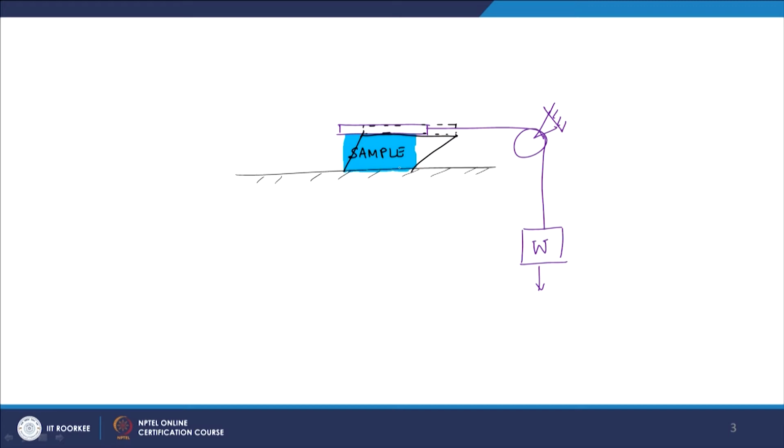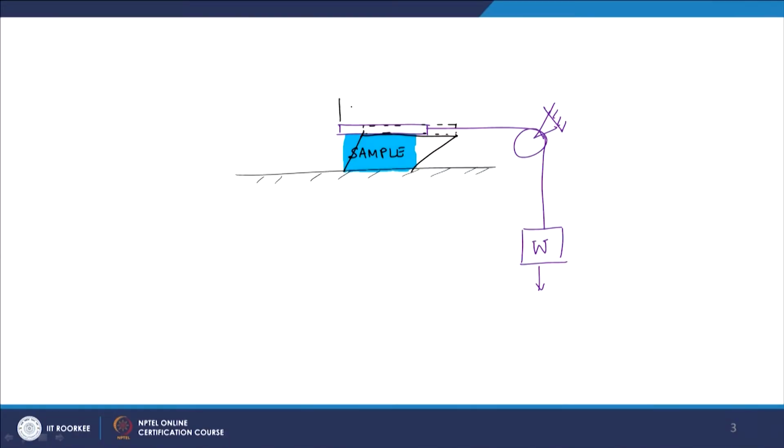That is the deformation that you are interested in. If I can measure the amount of shear for a unit length of sample, I can get the deformation for a certain shear. If I do the same thing with time, that is, if I am shearing at a certain rate and I find the amount of shear divided by the time, we get the shear rate, and that would give me the force or stress I have to apply to pull at a certain shear rate.